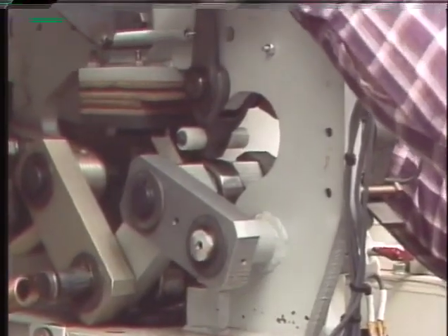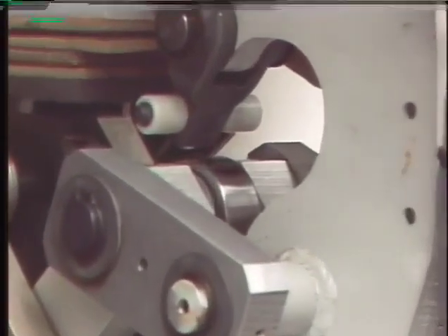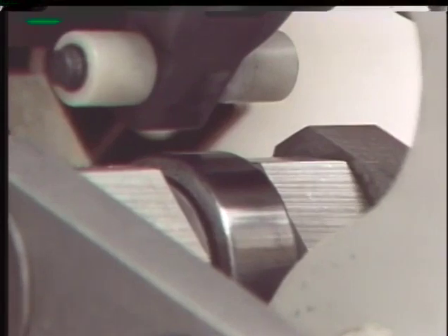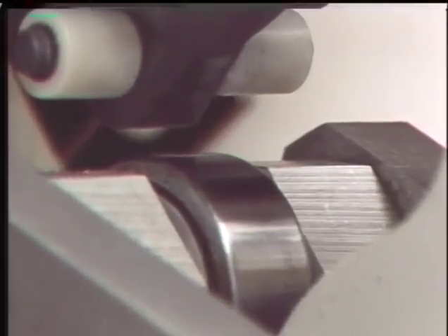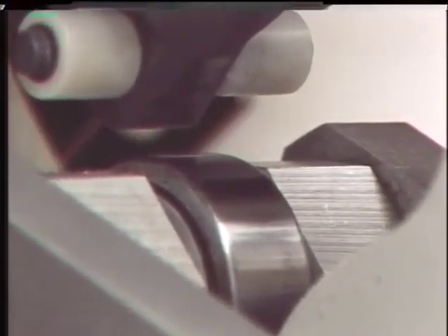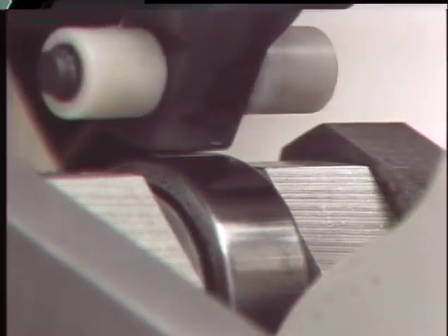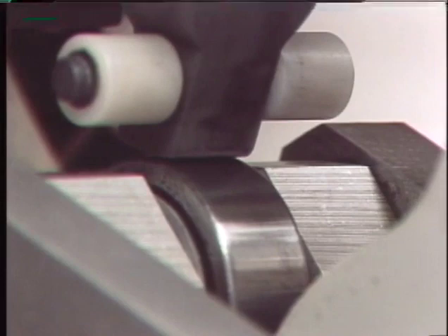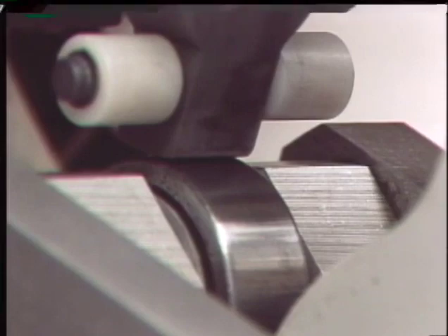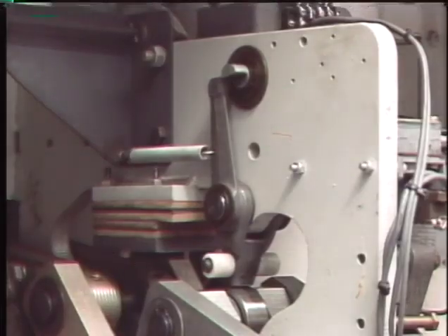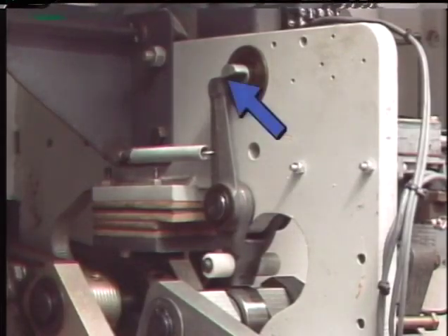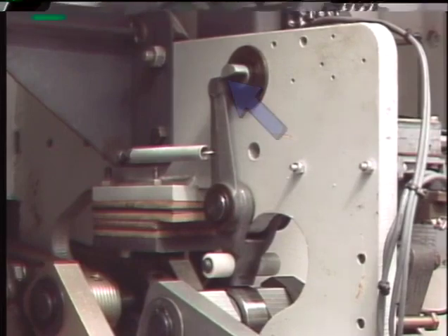Numerous mechanism adjustment checks are also made with the breaker closed. Two of these are latch wipe and latch clearance. Latch wipe is a measurement of how much of the surface of a latch rests against a roller or other component to hold the operating mechanisms in place. Latch wipe can be checked in different ways. Sometimes, visually checking that the latch rests against a stop is all that's needed.